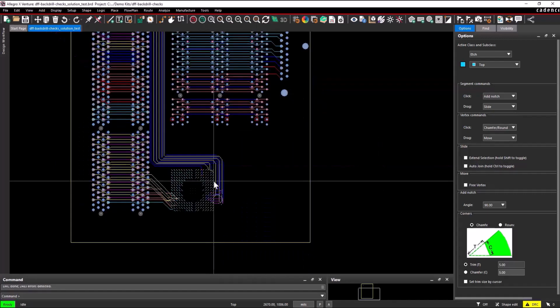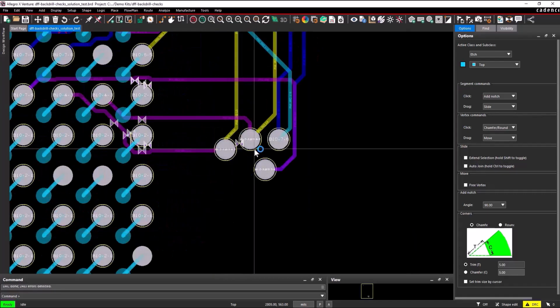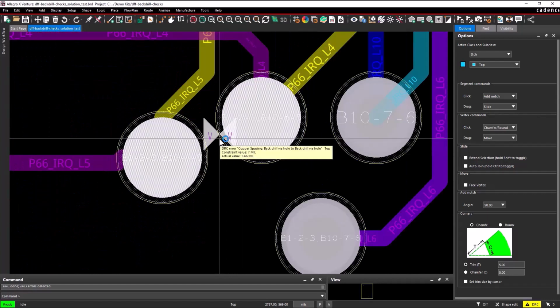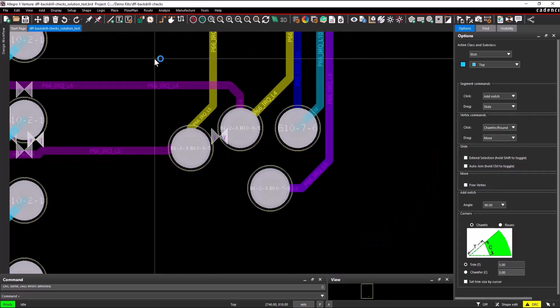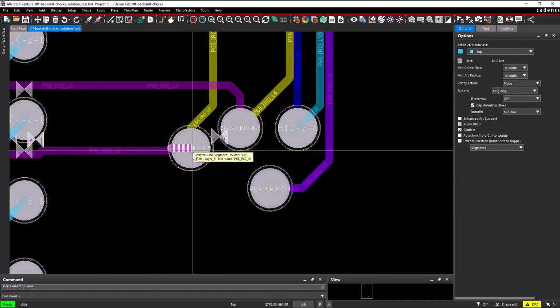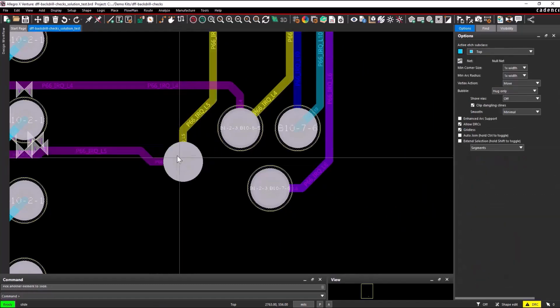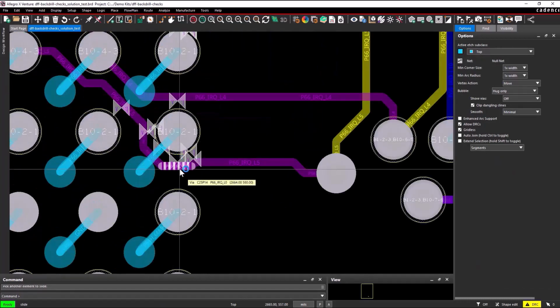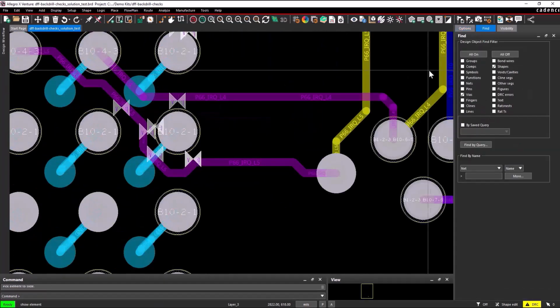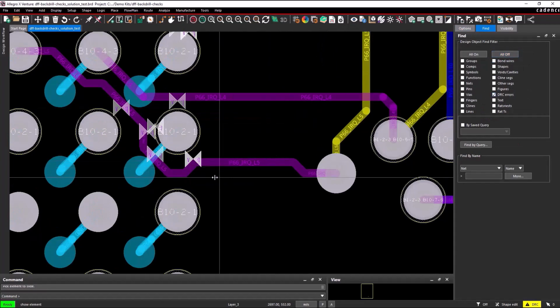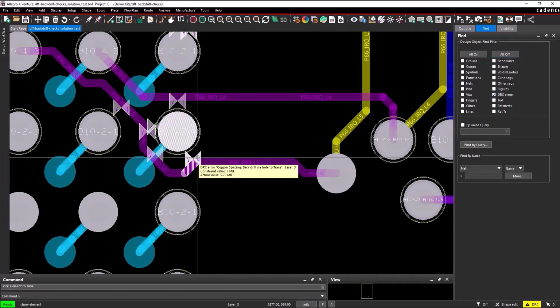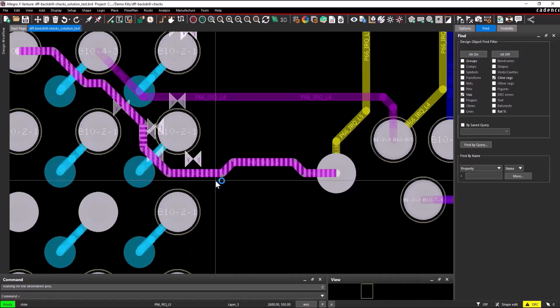Now probe the DRC errors nearer to backdrill pins, via, and C lines. You can observe the DRC errors for spacing violations between backdrill via to backdrill via. Now, you can move the tracks and vias using the slide command. Now, I am probing one more DRC error that shows backdrill via to copper spacing error. Again, I use the slide option to clear this DRC error.